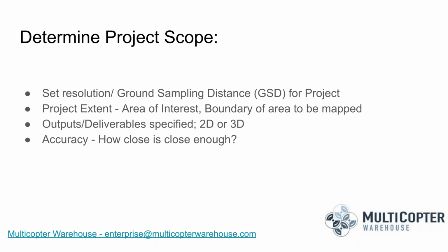The other side of that is no, because there's no software development kit for the Mavic Air 2, so there's no way to automate the photo taking to make sure that you're getting proper overlap from image to image. Now, I don't know if DJI is going to come out with that at some point, but they have not announced it. So today, as it sits, the Mavic Air 2 is not a good mapping drone because it can't be automated to make sure you're getting enough images. Having said that, there is a way to manually capture images to get a successful flight.